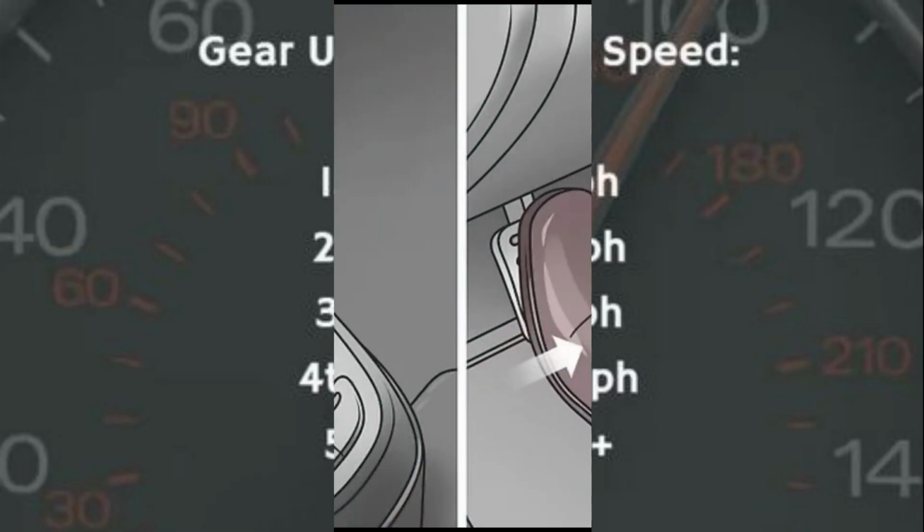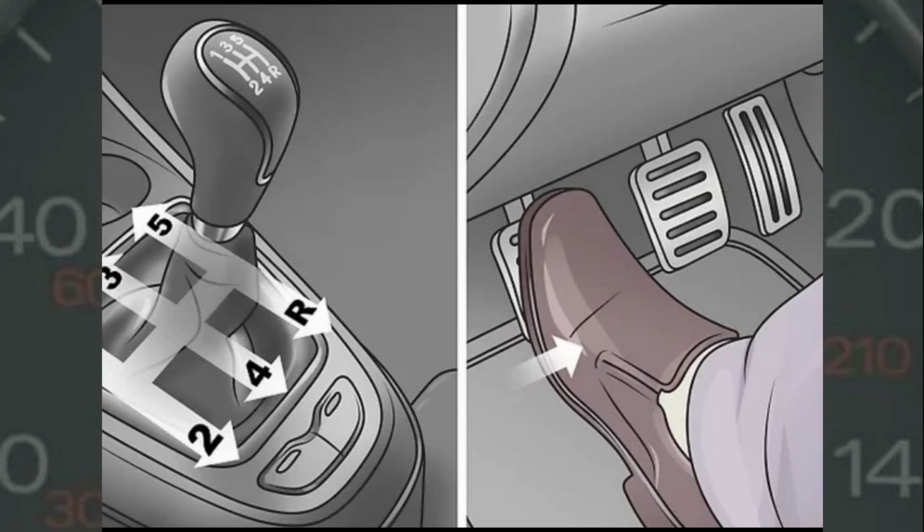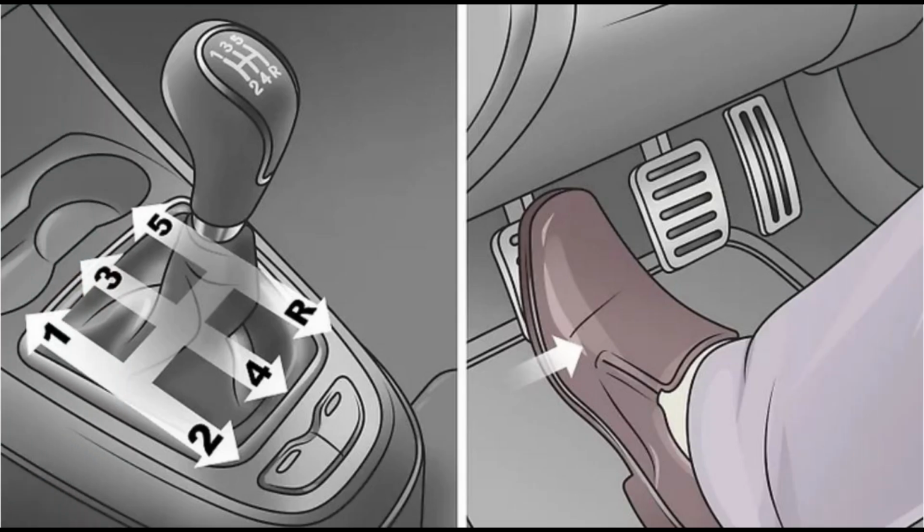The gear stick, also known as the gear lever, is a lever that allows the driver to change gears in a manual transmission vehicle. It is mechanically connected to the gearbox and enables the driver to select the appropriate gear to match the driving conditions. By changing gears, the driver can control the amount of power transmitted from the engine to the wheels. For instance, lower gears such as first and second provide more torque, which is useful for starting the car from a standstill or climbing hills, while higher gears are used for cruising at higher speeds and improving fuel efficiency.